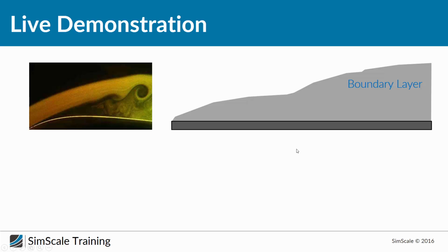And there's a last thing we should talk about when we're talking about turbulence modeling. It's again the boundary layer. And as we talked about in the first session, the boundary layer is defined as a very thin layer between the physical surface and the free stream, and everywhere where flow velocity is smaller than 99% of the free stream, we're talking about the boundary layer.